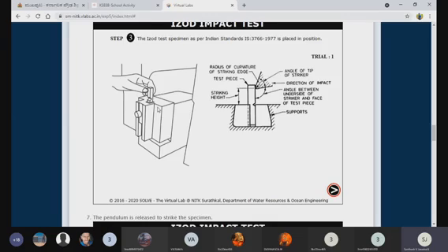Have you seen a knife? That edge looks like a knife, knife sharp. So once we release the pendulum, that sharp edge will hit this workpiece through this notch. Once we release the pendulum, immediately that impact load or sudden load hits the workpiece.